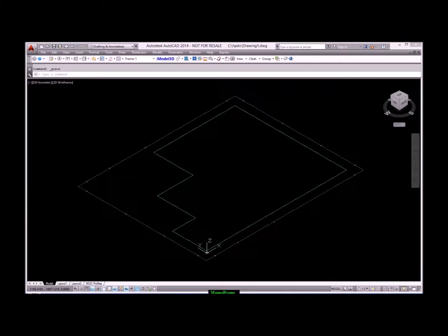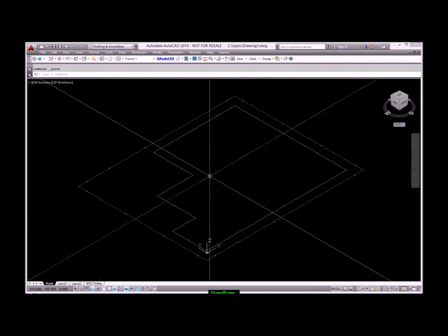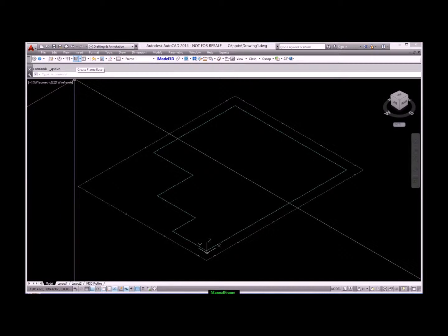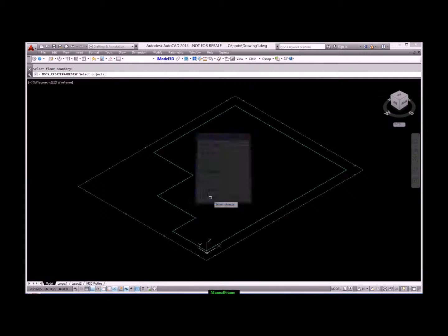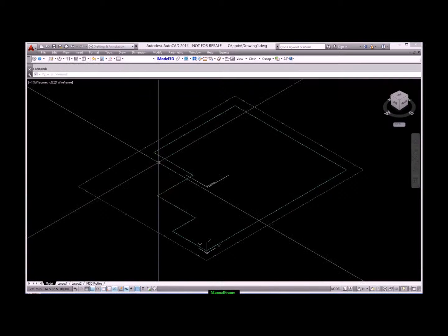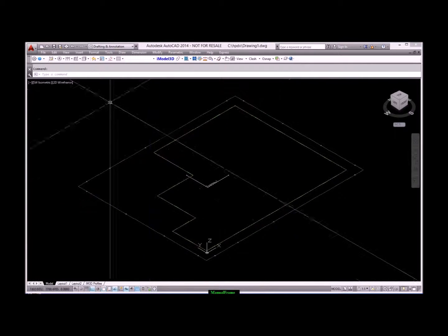Create manual space frame. IM3D space frames are basically used to facilitate modeling concrete and steel structural members as well as applying load cases. Auto load distribution and structural analysis can then be performed globally to all structural members. There are two ways you can create a space frame, one is automatic and the other is manual.